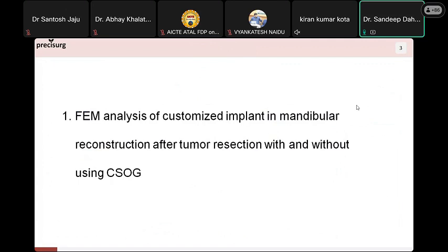So here we perform dynamic analysis. When we compare the results obtained with this loading and boundary conditions, you can see that with the standard implant, in the case of normal walking, the result obtained is around 175 megapascal, which is only around 89 in the case of the customized implant. In the case of slow walking, it is around 178, and in custom, around 91.